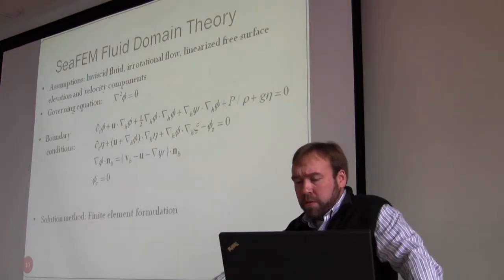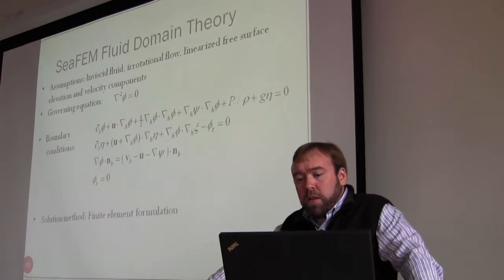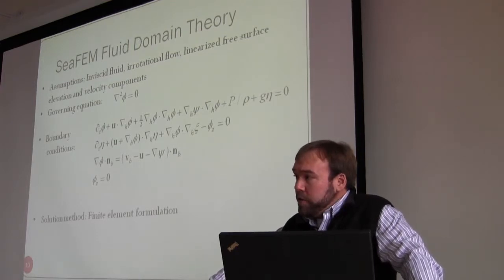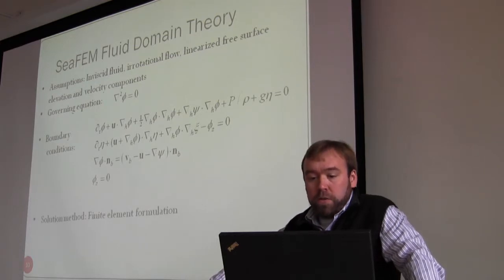Simple. Okay, so now let's talk about the CFEM simulation. And first we'll start talking about the fluid domain theory, which everyone has seen before, I'm sure. Inviscid, irrotational, linearized free surface, and velocity components. Thus, the governing equation in the domain is the Laplace equation. Boundary conditions, I think you've all seen before. Dynamic boundary condition on the free surface and kinematic boundary condition on the free surface, the first two equations.